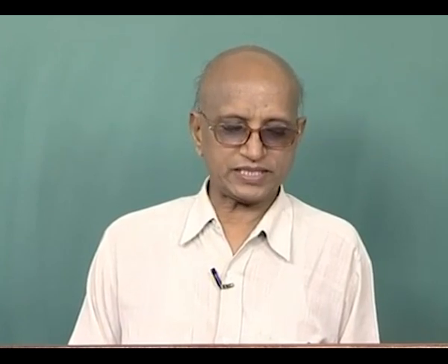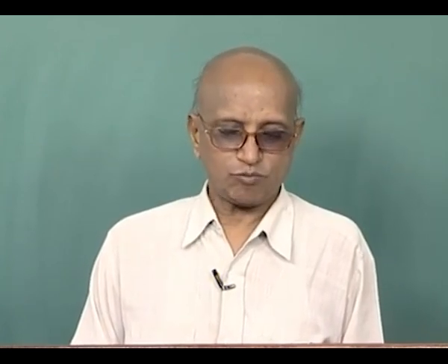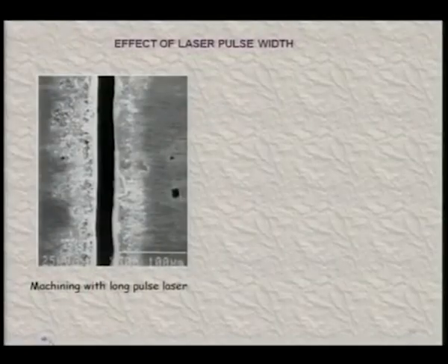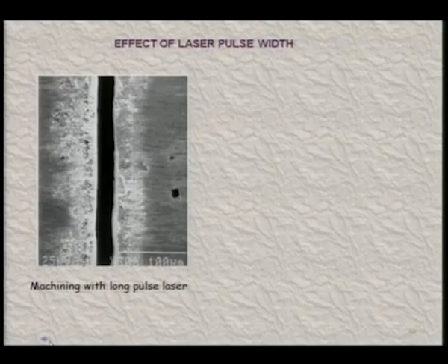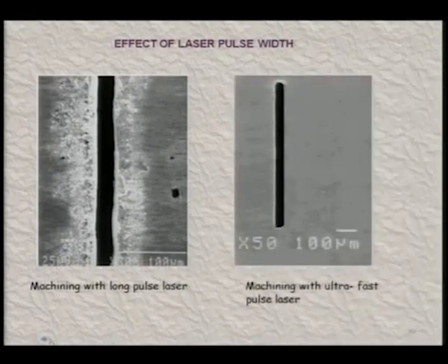Machining with a long pulse laser, you can see the irregularities, whatsoever small it may be. Although these are very fine, very small irregularities as long as micro machining or micro parts are concerned, still irregularity is there when you are using the long pulse laser. But if you use the short pulse laser, you can clearly see the difference in the quality of these two grooves that have been made on a similar kind of workpiece.